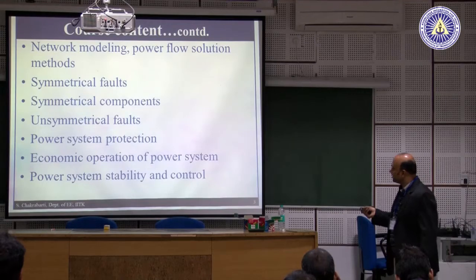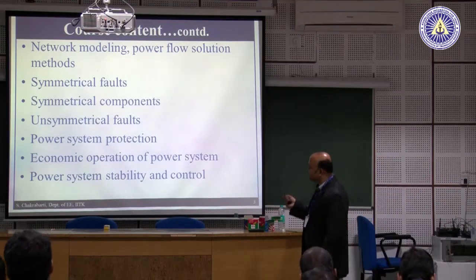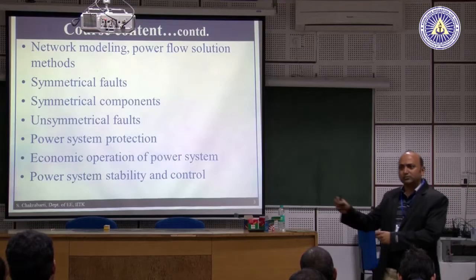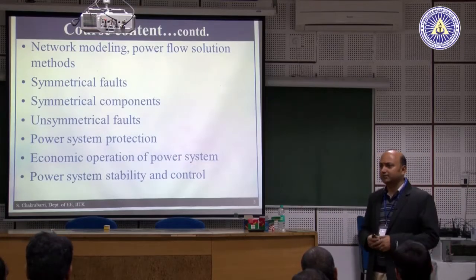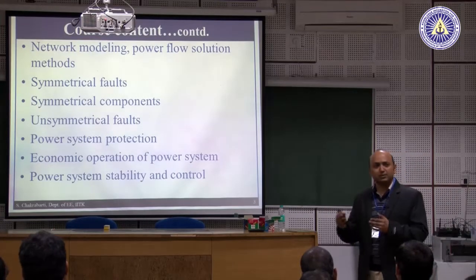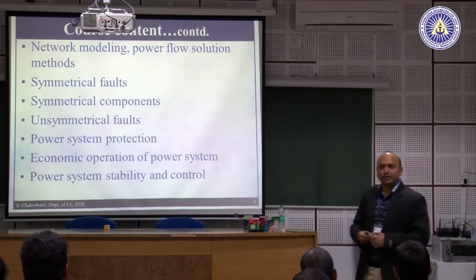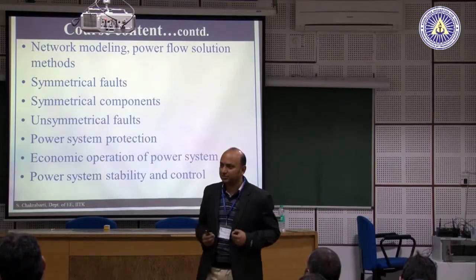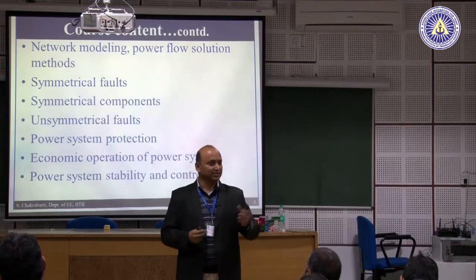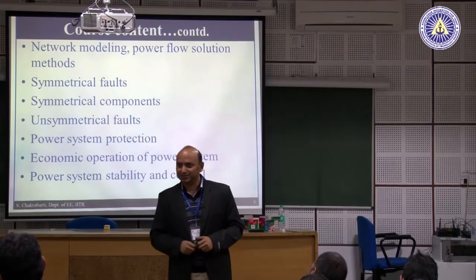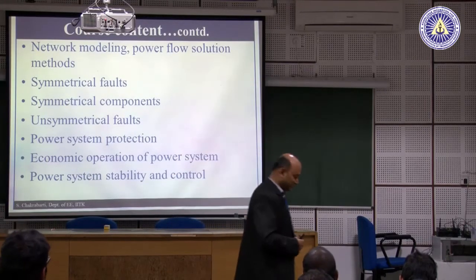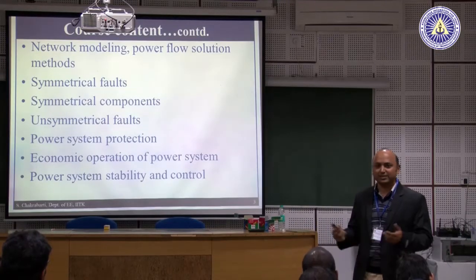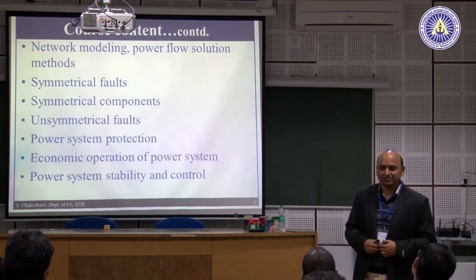And when you do this, what I have seen from my personal experience is that students very easily get carried away by those equations without really getting the physical concept. For example, in interviews when you ask them what are the different types of buses you consider in a power flow solution, the ready-made answer is PQ bus, PV bus, and V delta bus, right. The next question we ask: how do you know what is the value of P in that particular bus? Nobody can answer. Okay.